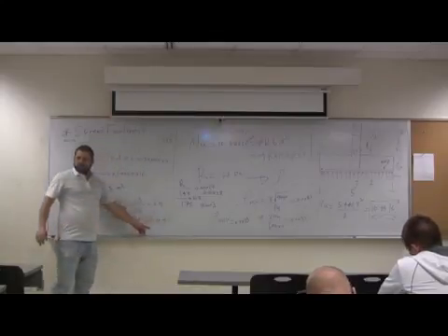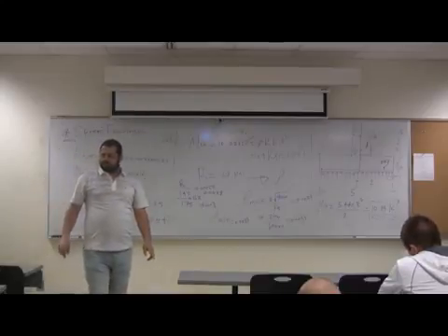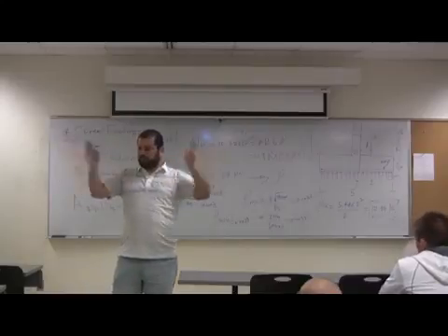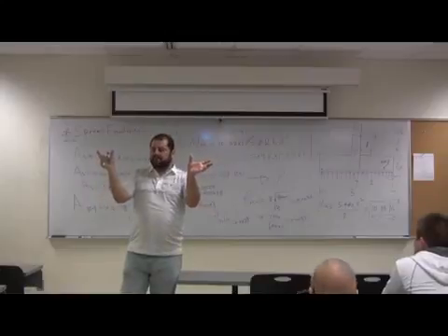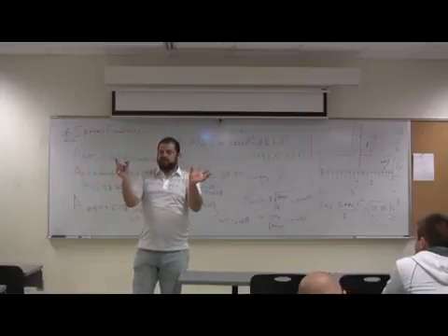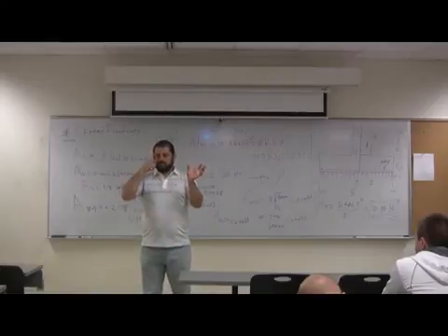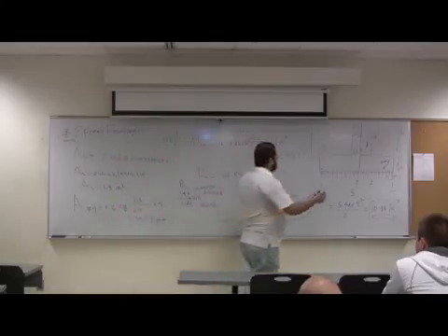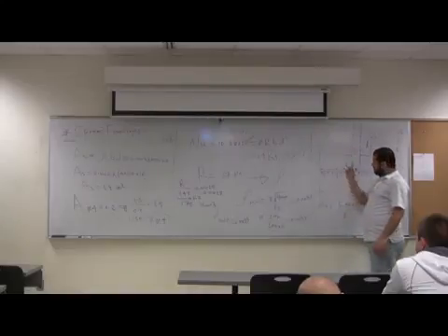7 number 4. What's the spacing between them? 7 bars in the longitudinal direction, and the width they will occupy is 4.5. Why are we still using 4.5? The 4.5 accounts for the cover on each side.